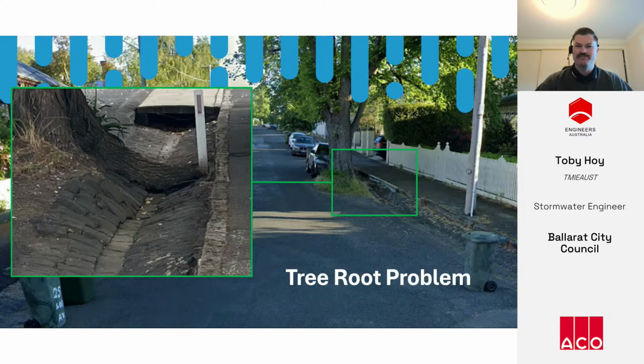Now for our drainage problem. As you can see, we have a tree root that over the course of a couple decades has grown through our bluestone open drain. This results in water and leaves being caught behind the root to about 250 millimetres of depth. This area has many deciduous trees, so leaves add to the problem significantly in autumn and early winter. A small amount of water gets beneath the tree root and into the ground between the bluestones, but this isn't enough to clear the ponding.